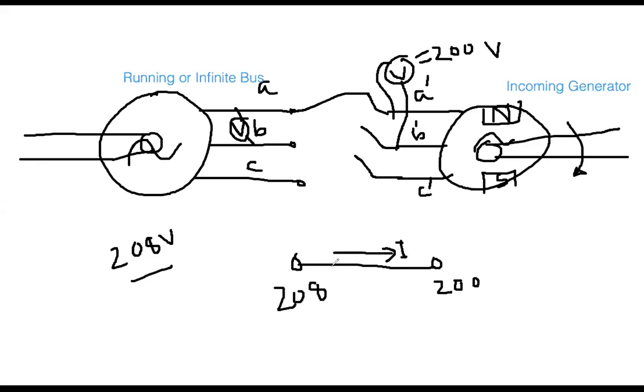And then if the current flows, definitely these connecting cables have, even a small resistance, they have resistance. So once current starts flowing, there will be I squared R loss, because even though it's small, there is some R between these two points. Therefore, there will be power loss. And what is the power loss? It will be exposed in terms of heat. Heat will be generated, which is not desired.